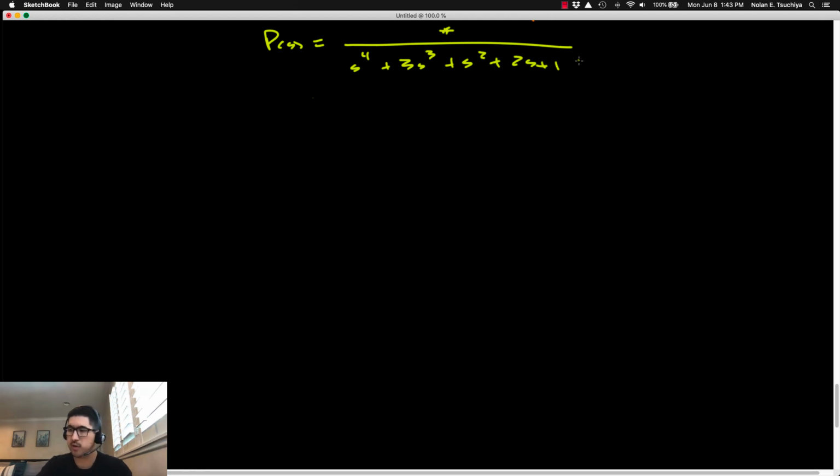Now all of the coefficients are positive, but it's higher than a second order system, so we cannot guarantee that it's stable, right? This is a maybe. We don't know if this is stable or not. It does have a chance of being stable because all the coefficients are positive, but that's not a guarantee. So what we have to do is apply the Routh test for stability, which means to construct the Routh table.